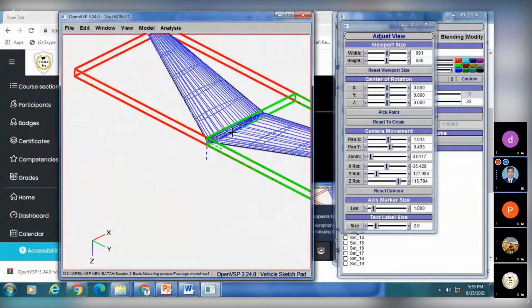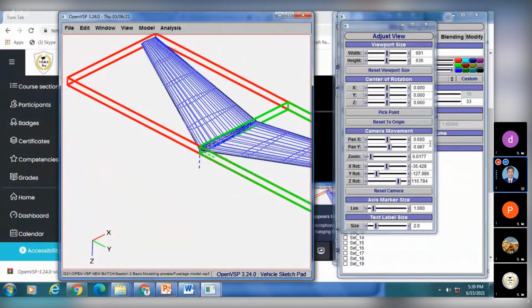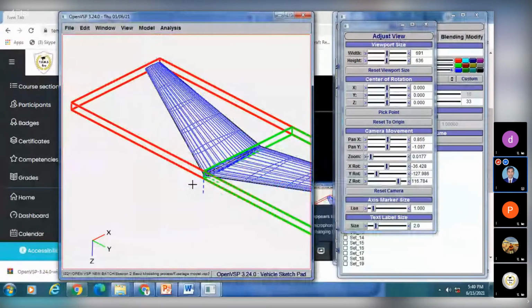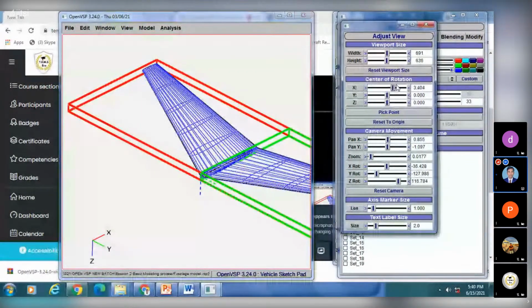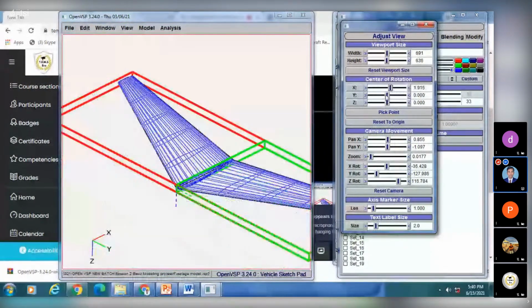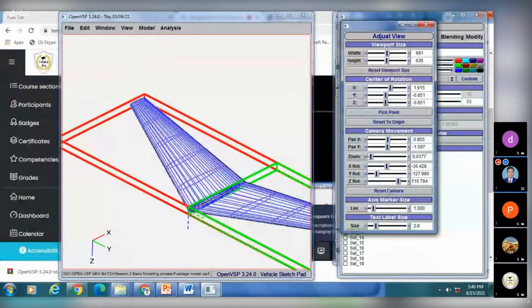With respect to this axis, if you want to place this model at some distance, you can type that value and enter, or else you can just use your mouse and place it where you want. Center of rotation, this also you can use along X, along Y, and along Z. I'll tell one by one.